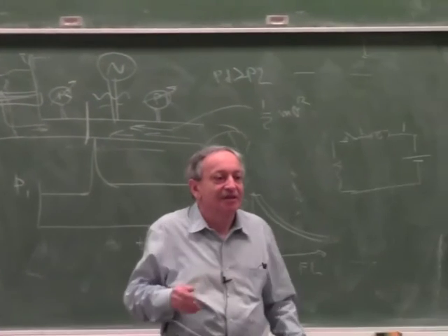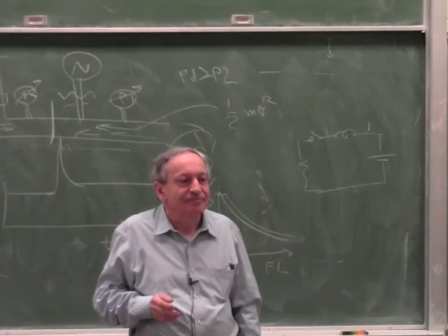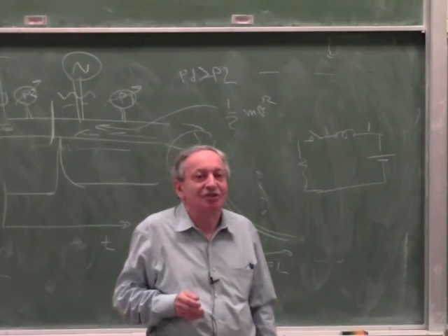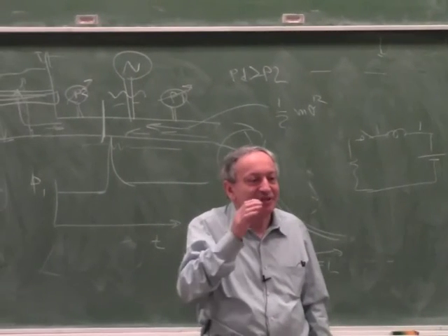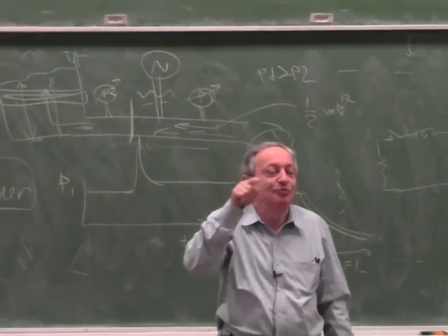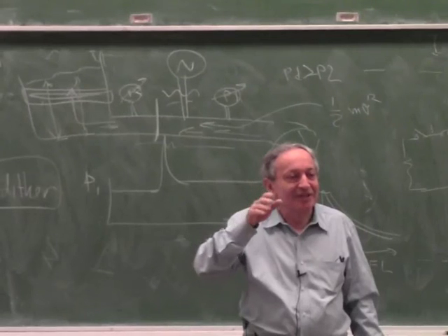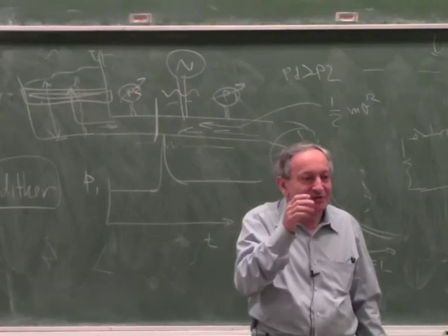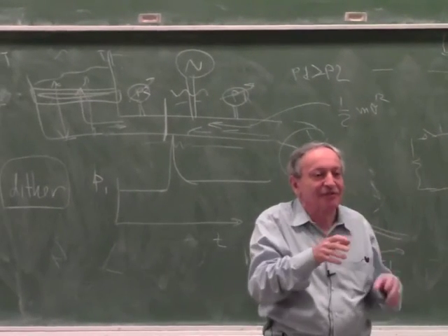Yes? Doesn't the mechanical device have to go through a point where it stops? You know, the thing moving up and down, when it changes direction, it has to stop. No, because it stops momentarily, but it's not enough to build up static friction. It vibrates. Any sine wave goes through two points. It stops in a cycle, but because it's still in motion, the velocity is zero, but at the point the velocity is zero, the acceleration is not zero. So basically, it doesn't really get static friction.